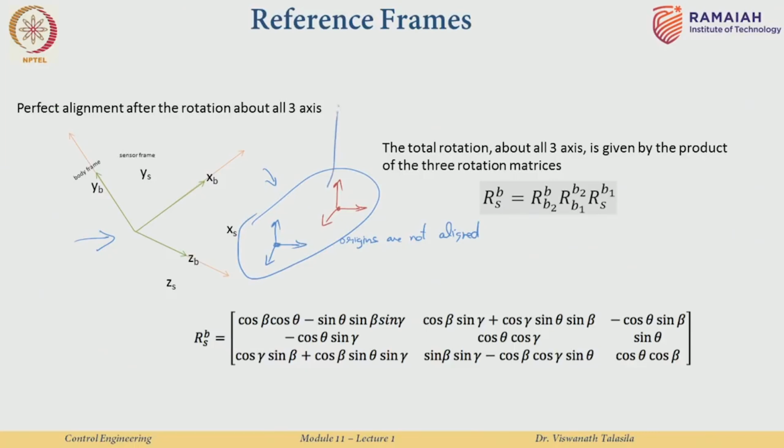This example we will write down over here and it is really straightforward. How we are going to do this is as follows. So, again we have the measurement in the sensor frame, ZS. The first thing we are going to do is to align the rotation axes, by multiplying with our matrix which we have already computed. After doing that, we shift. So, I will actually draw this over here.